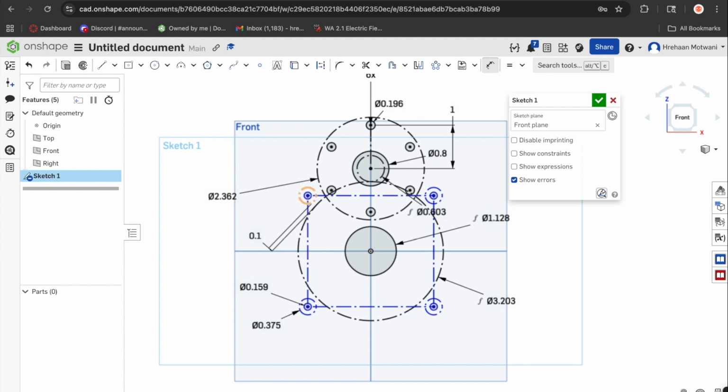And then you want to create the outside of your plate. You generally want to make your plates as small as possible. You don't want any excess material, because that adds weight and takes up more material. So you're just going to have this tangent here, and then you're just going to tangent these lines all around after you make them.